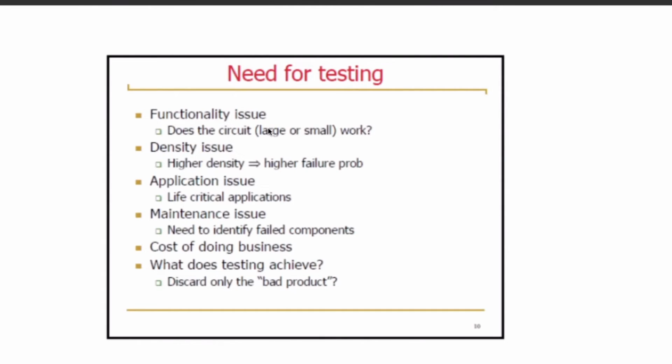So functionality is an issue; we need to do the verification. Then there is density: if we have a complex design, we have faults at multiple locations, so the density of faults will increase, and it will be difficult to generate that many test patterns. Test generation will be challenging for those types of designs.